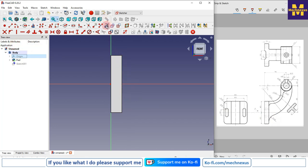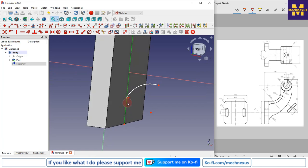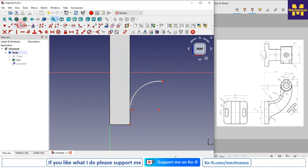Before drawing this radius I will project this outer edge, and then I will select the 3-point arc, and this arc will be tangent. The edge is not visible because it is in the mid section, so we will switch to the wireframe view.